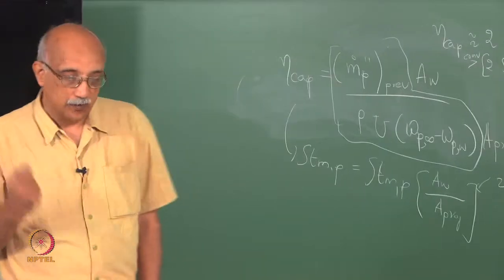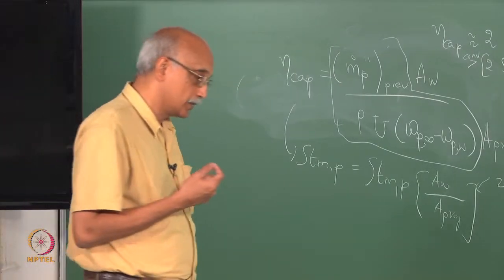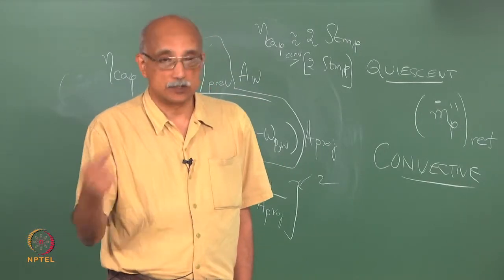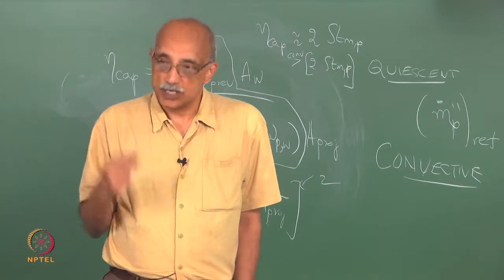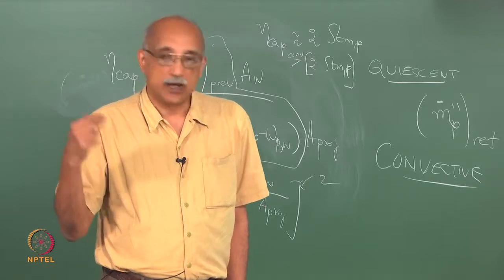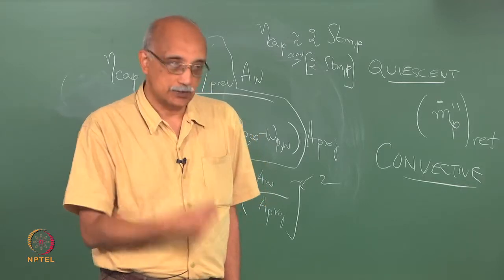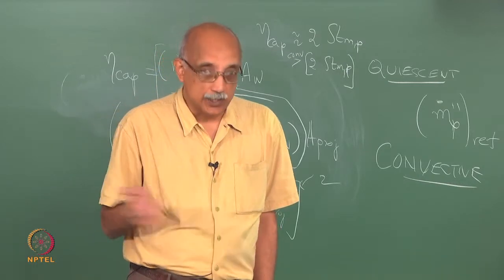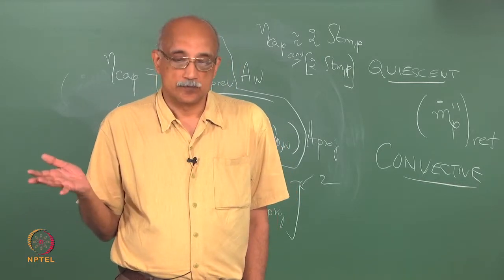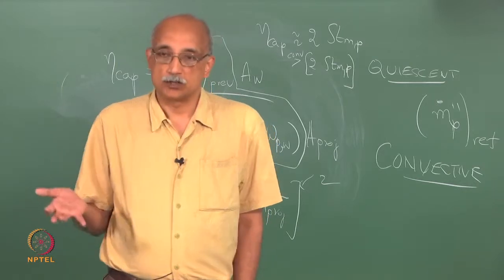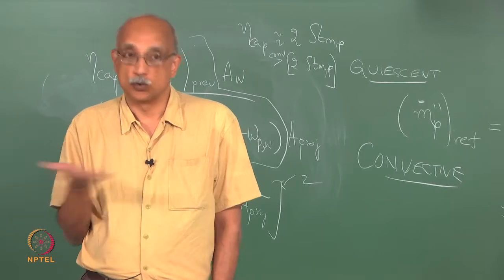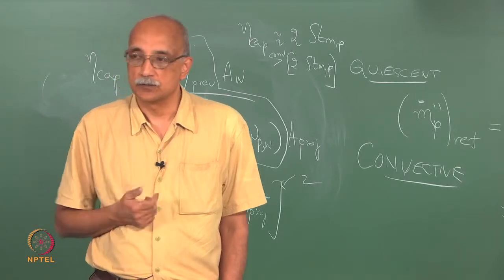And the fact that the dependence of the terminal velocity on particle size changes as you go from the micron sizes to submicron sizes to nano sizes. In fact, as you approach the nano dimensions, the time that a particle takes to settle can quickly become infinity. It can just start floating essentially in the fluid, right.